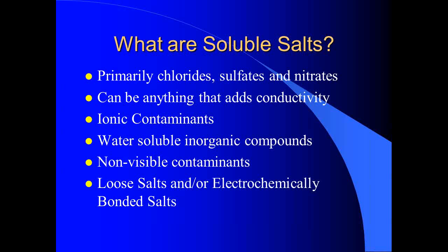What we typically encounter in salts is sodium chloride. The chloride is bonded to the sodium. It really prefers steel. It likes zinc even better. But what the chloride ion will do is disassociate from the sodium and bond to the steel.